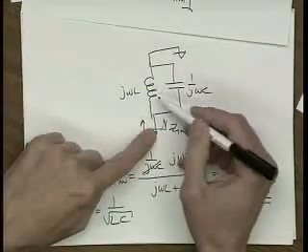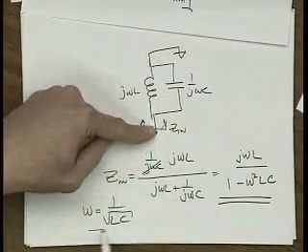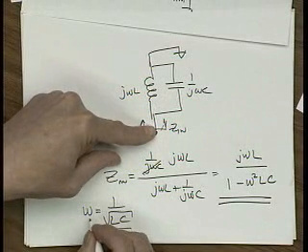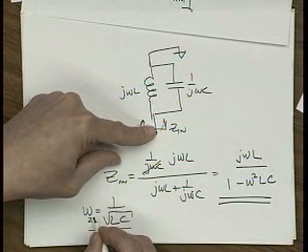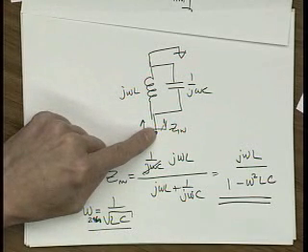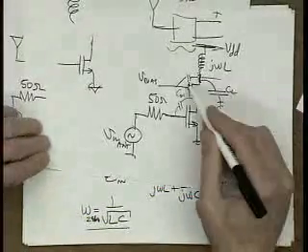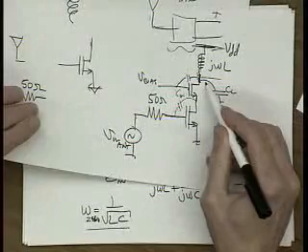It's called a tank circuit. So let's make this at 2.4 gigahertz. At 2.4 gigahertz, right in the center of the band we're interested in, we can effectively get rid of all this capacitance that's hanging off that node.